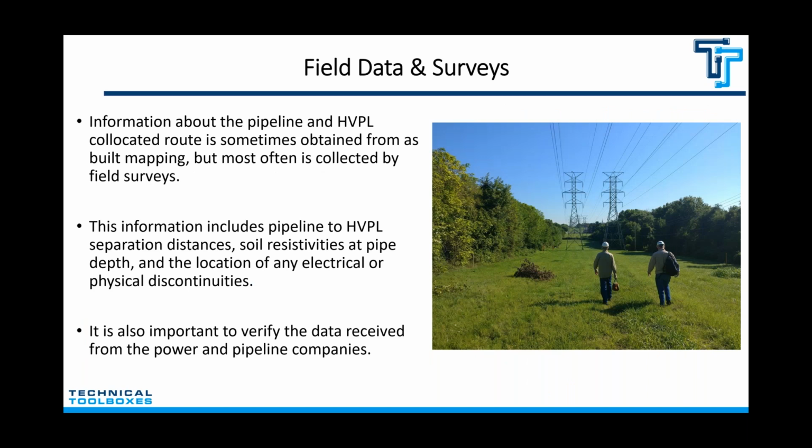Field surveys. So we request that from them. We also go out and do field surveys. The main thing we do out in the field is collect all the data we can. We're going to measure the wire heights, and we'll get GPS readings of all the above ground components and where the towers are and anything else that might be of interest to us out there. We'll collect all that data and bring it back to the office for our modeling. And even if we get some of that data from the power company or the pipeline company, we'll use our field survey to verify the data that we get. Okay.